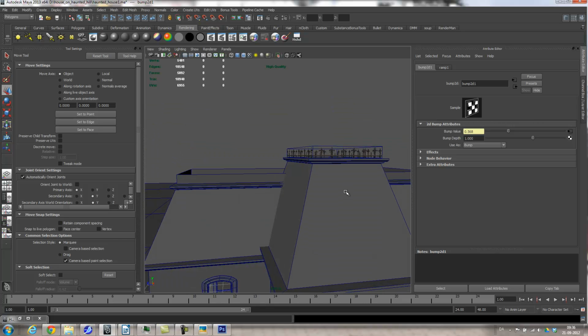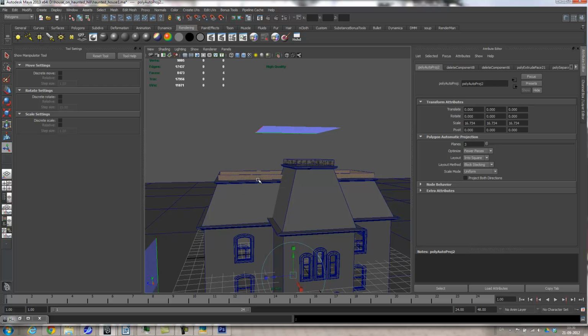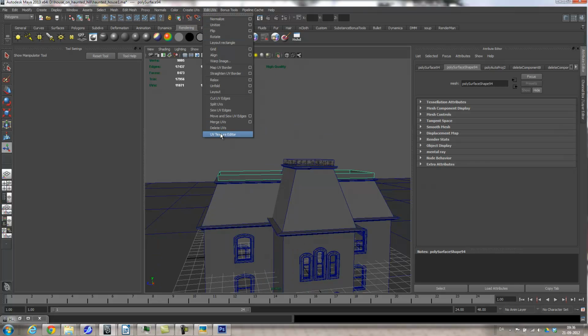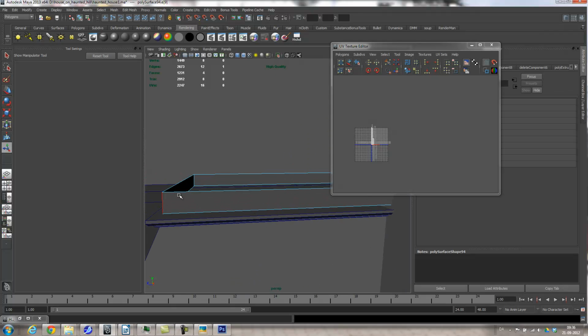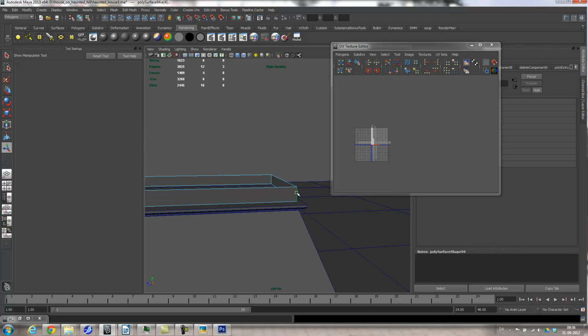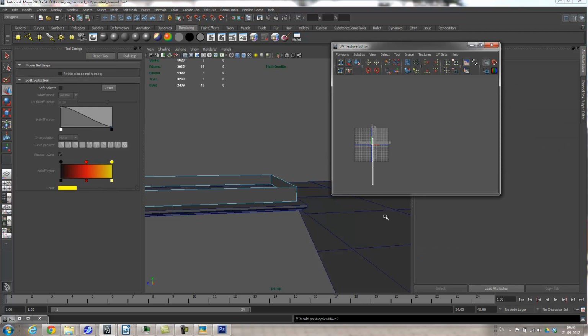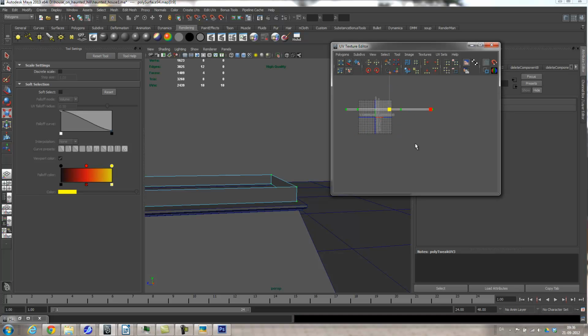So that's one of them. And I'll just do the next one fast so you can see what's going on. So create UVs, automatic mapping, grab that, go to my UV texture editor, grab the edges here, so grab that one, and that one. So I'll leave one because I can't attach it all the way around, because then it will loop. So I need to have one where it's open, and then attach them like this. Go to UVs, select this, flip this around, and then move it up, make this bigger.